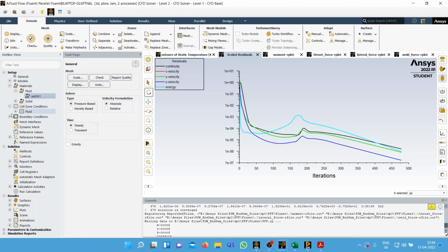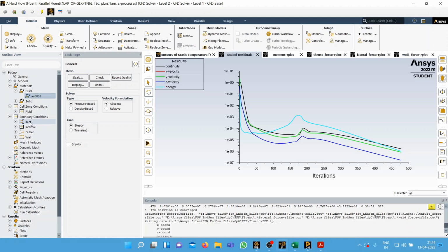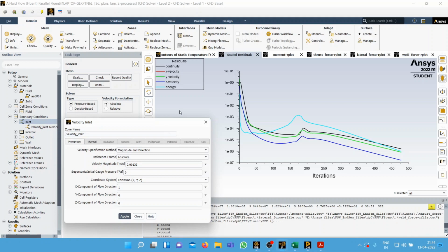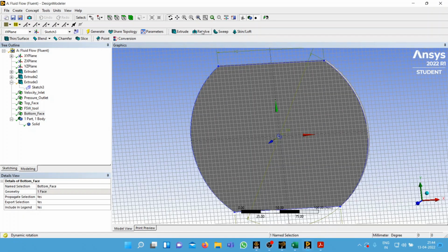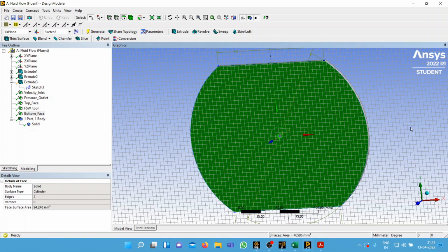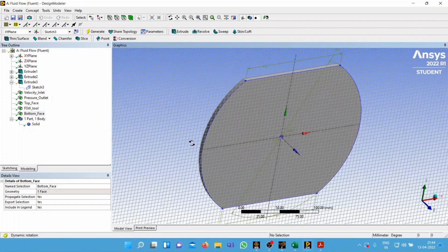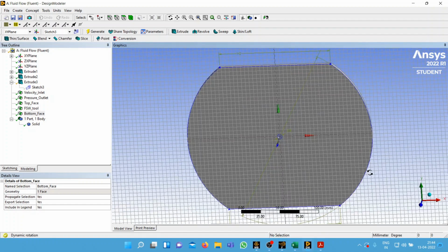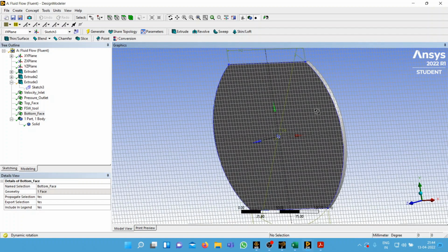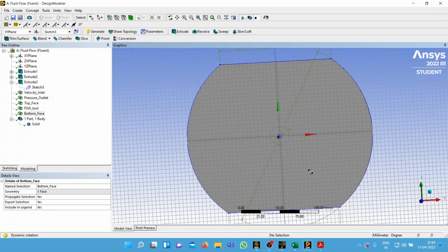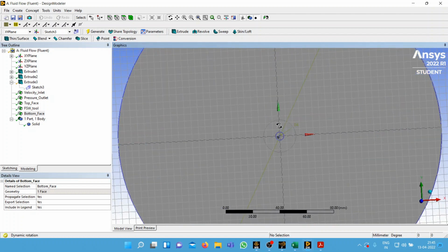And then let me take you through the boundary conditions that I have assigned. Generally, some time before I showed you which is the inlet portion, outlet portion. Again, let me show you. This is going to be the inlet portion, and here the velocity is given. It is to be prescribed, and this is the output region, where the pressure is to be specified. And this is the top face, and this is the tool region, the small one.